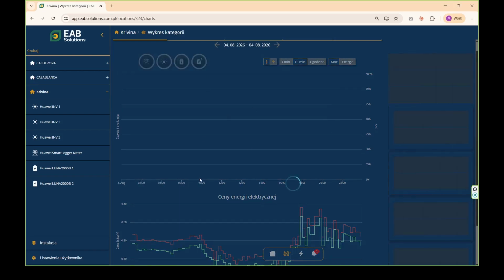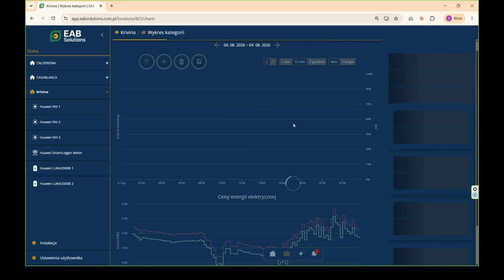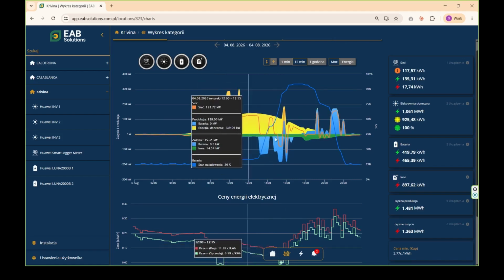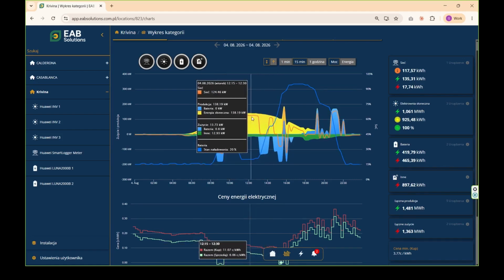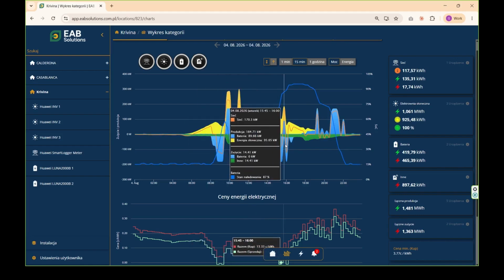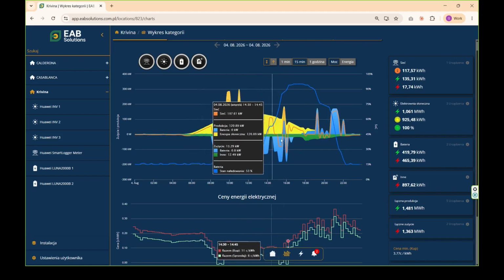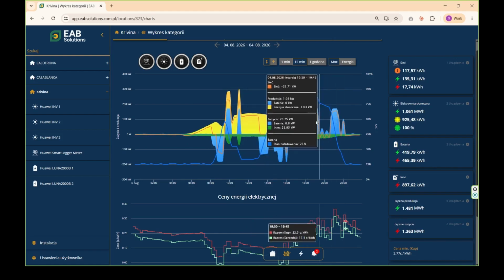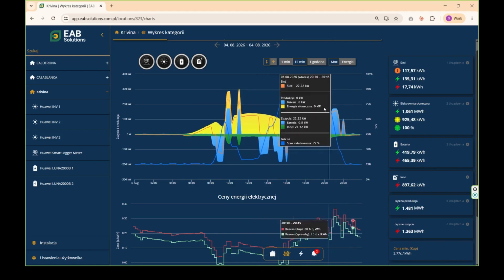Basically, with PV producing in the middle hours of the day, you're already reducing the client's grid consumption, because the client will consume part of that production. And on top of that, if there's PV surplus or a cheap tariff, you'll be able to charge the battery to erase their consumption inside this window, especially in this zone between 8 and 10 at night, which tends to be the most expensive and is still inside the opłata mocowa window.